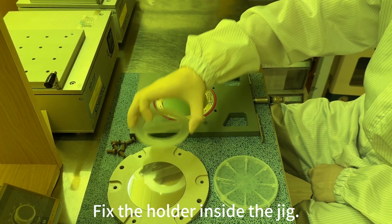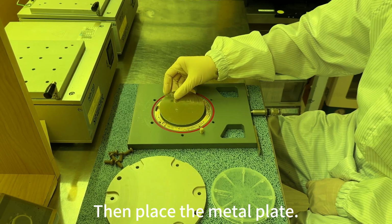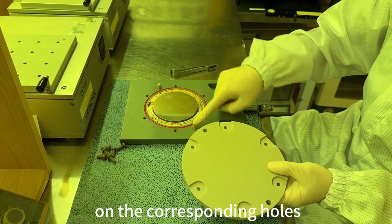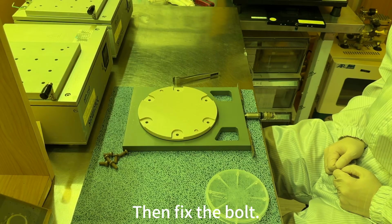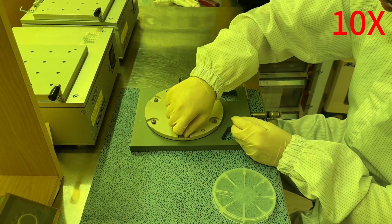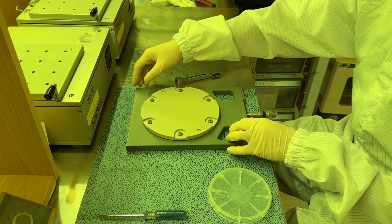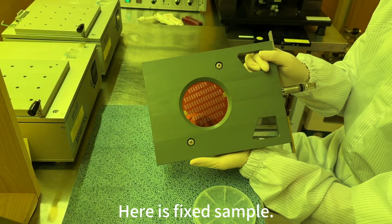Fix the holder inside the jig. Then place the metal plate. Place the plastic cover plate on the corresponding holes. Then fix the bolt. Please note that the bolts should not be too tight, or the wafer will be damaged. Here is fixed sample.